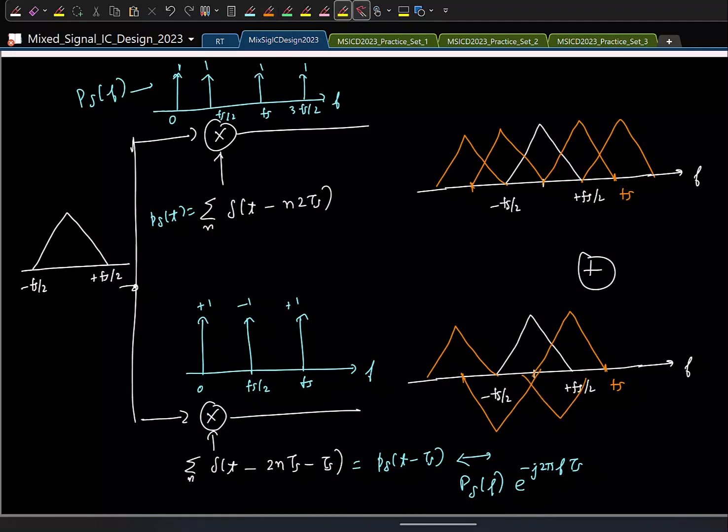So now if I add these, what will happen? Basically, I'm adding these two. So these will get cancelled with these. So note that in this case, each individual ADC has terrible aliasing, but when you add these multiple parts, those image frequencies will get cancelled. And in particular, if let us say the input is a sinusoid at Fn, the image will be located at what frequencies?